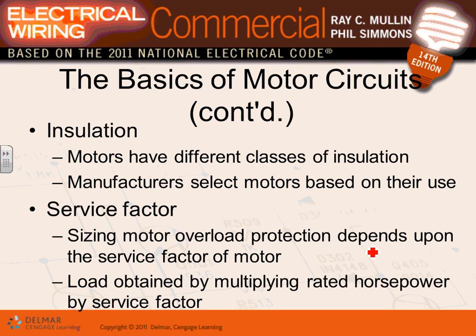A tiny little thermal heater heats a device, it melts, it opens, to de-energize the equipment and protect it from being burned. I'll show you what happens if you don't have it. We have nice pictures, guys, in this book. What happens if you don't have overload protection? Insulation. I'll talk about insulation, guys.